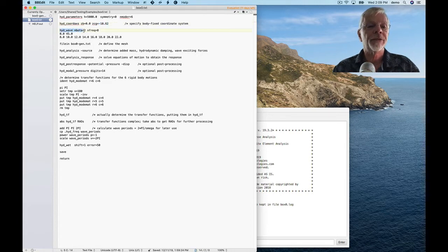The next command defines the wave angles and the wave periods. In beta equal, we're going to be using 2 wave angles and 8 wave periods or frequencies. In this case, we're inputting periods, even though the ID shows it says frequencies. One can either input periods or frequencies, but the syntax we're using here is for periods.